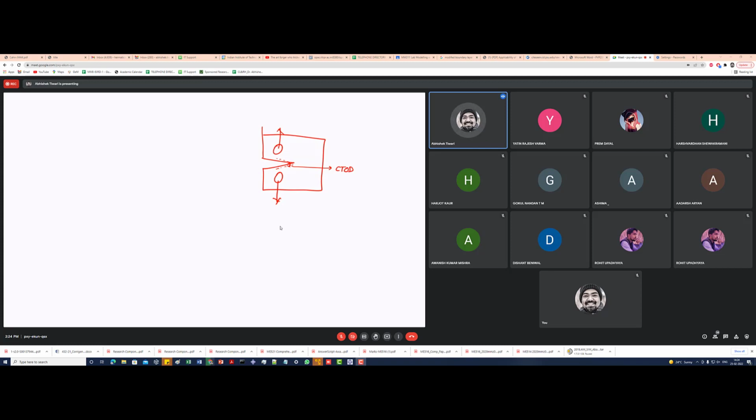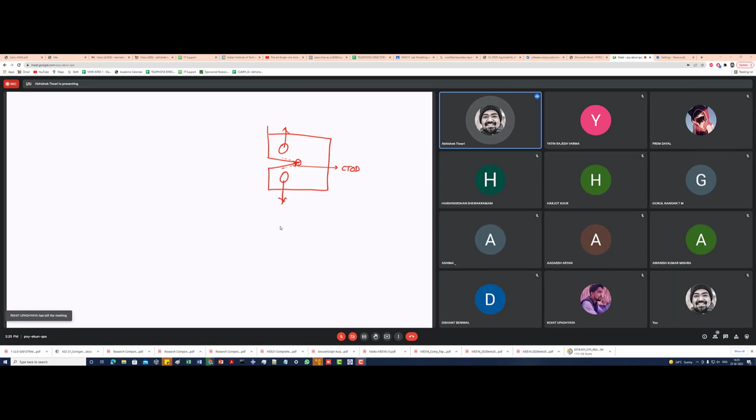When you do finite element simulation, you should know the size of your process zone, because there the stress and strain values will be wrong. That is number one. You also have to get the stress and strain at a very small volume at the crack tip.